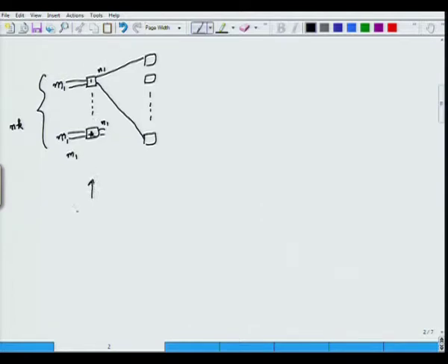So, all switches which were here were m1 by n1 switches, and I was using k1 of them. Then I was using in the middle stage k2 switches of m2 by n2 size, and then there was a third stage configuration, third stage switches, where I will be using m3 by n3, and there were k3 such switches. The condition is that free incoming ports are available only in the first stage, and free outgoing ports are available only in the last stage, which is the third one in this case, or the output stage.